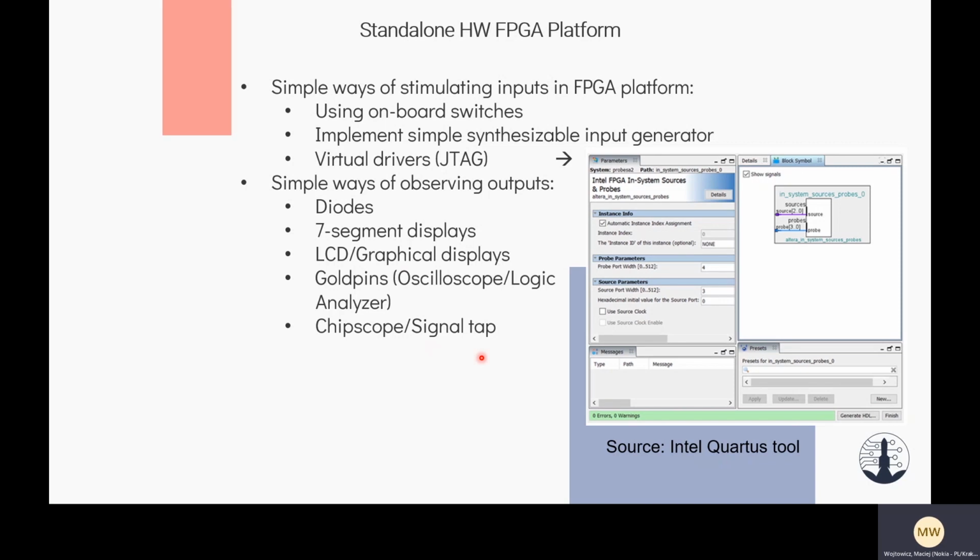that automatically drag out some internal signals into the output of your design and use other FPGA resources to connect all the signals to some visualization part of the software, and the values of these signals in time can go through the JTAG interface, this time from the FPGA board into the software, and in this way you can debug your design effectively, similarly as you could do in normal simulation. Of course, for a complex design, you are not able to observe all the internal signals, so it is reasonable to select just some groups that are useful for debugging issues in the FPGA.